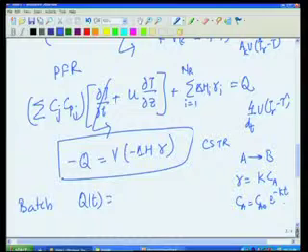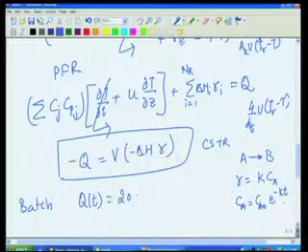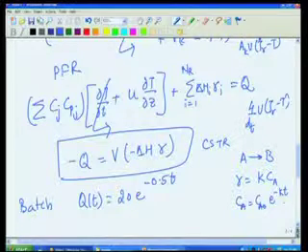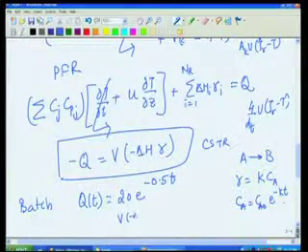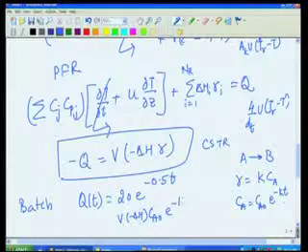So, if I take all this together, that is concentration decreasing exponentially with time, and put it back into this, my heat of removal will be V (minus delta H) Ca0 e raised to minus kt into k value. I am just putting some numbers, it does not mean so much at this point.